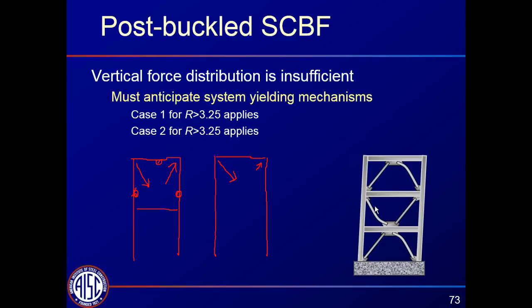And the reason is, as we go into large lateral deflections, the braces in compression are buckling. And as we go out to larger and larger drift, they buckle and they bend. It's kind of like a flexural plastic hinge might form in the middle of these braces in compression when they get out to large enough drift. And they never quite work the same in compression again. So as the earthquake goes on and they buckle 2, 3, 5 times, they get softer and softer in compression, and they get less and less effective.